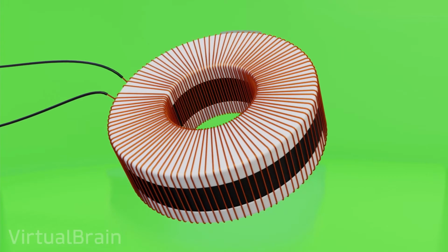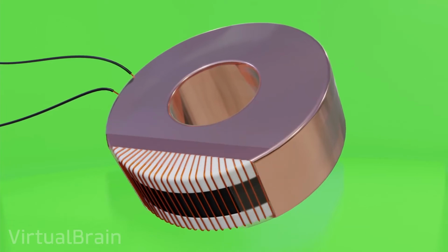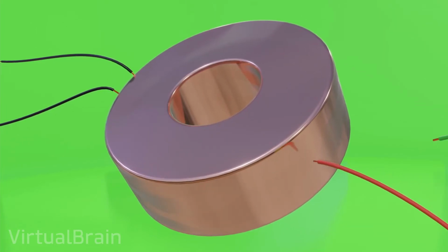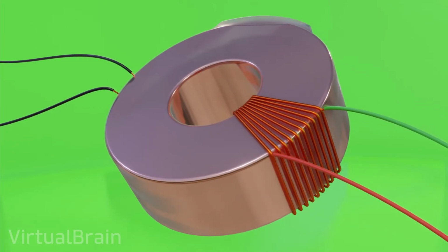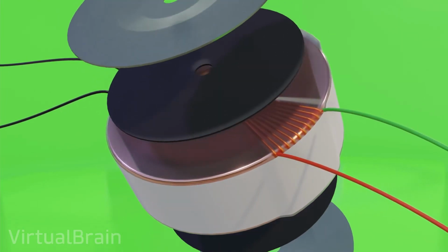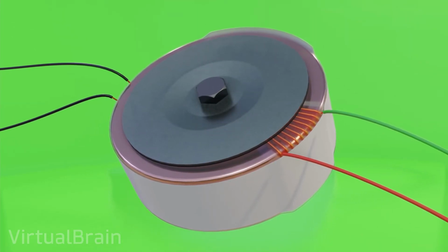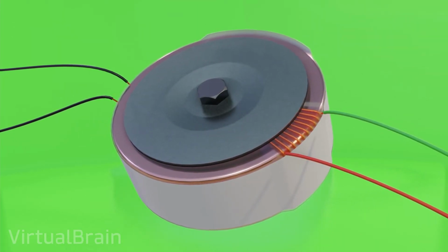Then, a series of layers are added on the primary winding to avoid direct contact and transmission of electricity with the secondary winding. Finally, after covering the set, two washers are usually added with a rubber separator to avoid damaging the cables, a bolt, and a nut, which together work like a press to hold everything together.